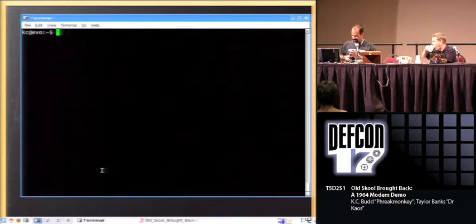I'm like, really? So an interesting thing about Bell 103 modulation, there's no handshaking. You don't have to get a carrier and do any kind of handshaking with an old modem. The new modems implemented all those features for all the baud rates. But the old original modems just turn bits into signals and what have you.